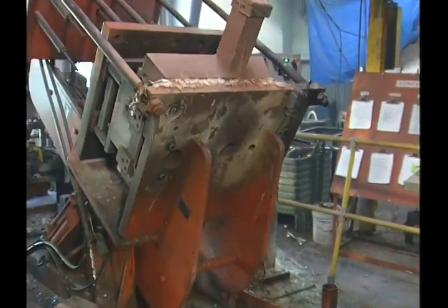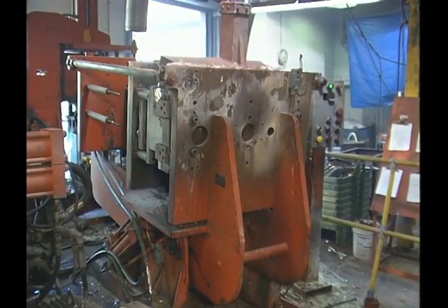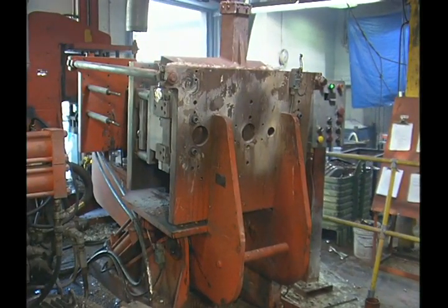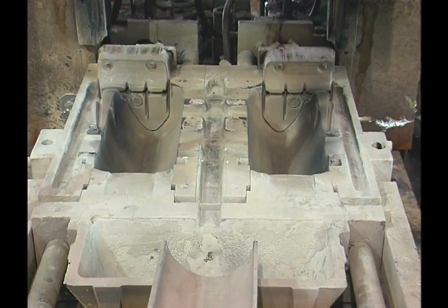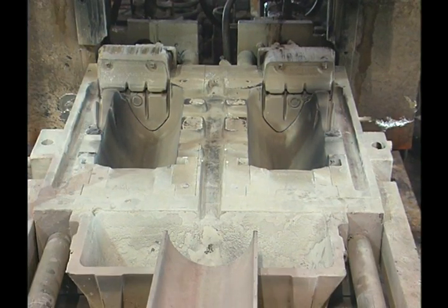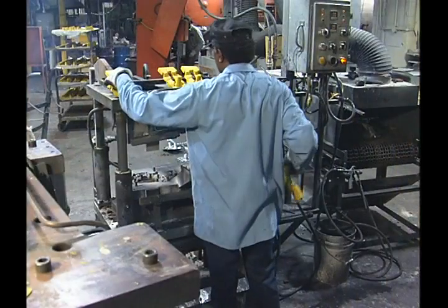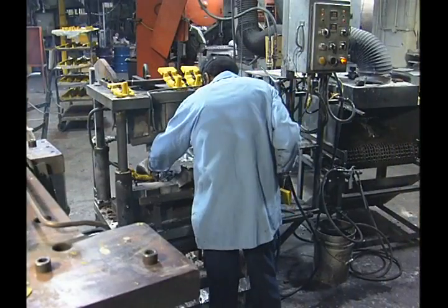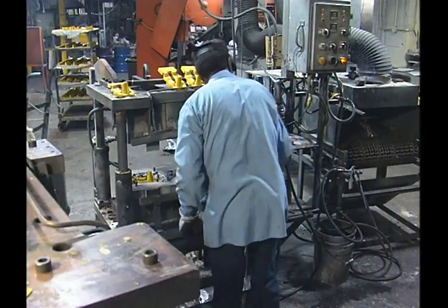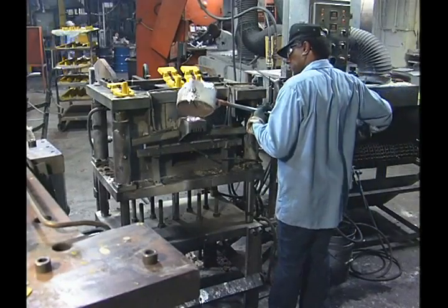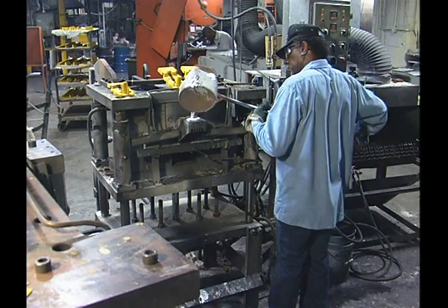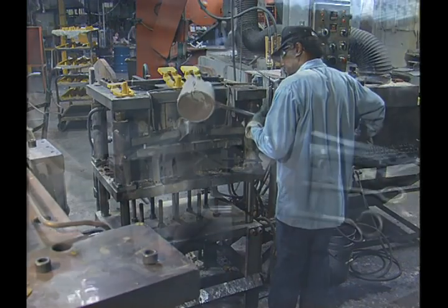Once poured, the casting is cooled by auxiliary heating and cooling systems. Cores used for permanent mold casting can be metal, operating in the mold, or made of sand or plaster and placed in the mold before it is closed. If sand or plaster cores are used, the process is called semi-permanent mold casting.